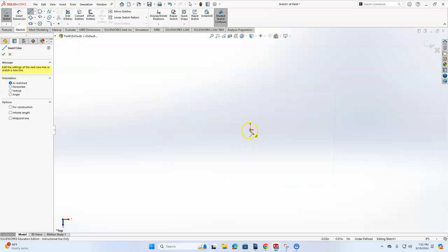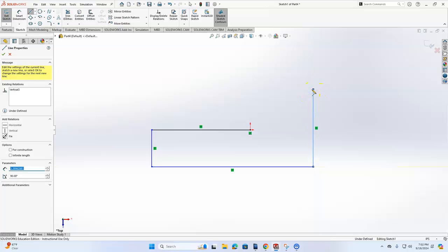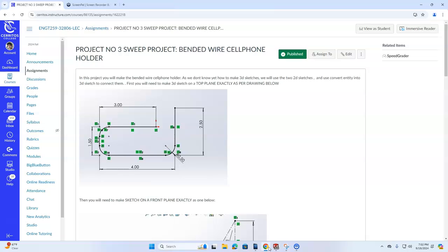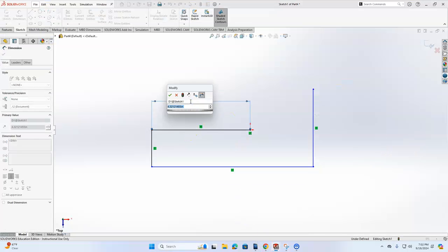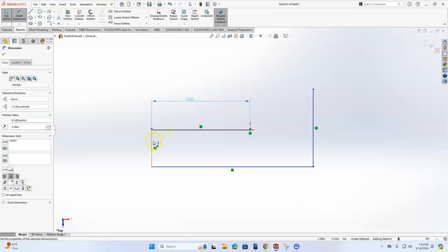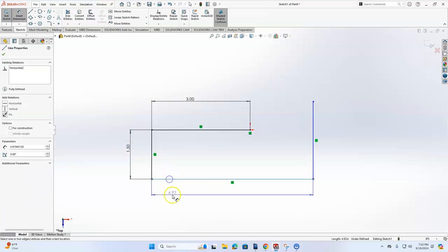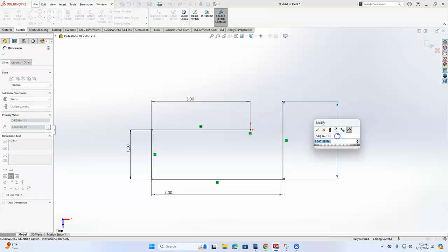Going to make a horizontal line left from the origin, then I'm going to make a line down, all horizontal and vertical, and I'm going to start putting in the dimensions like 3, 1.5, 4, so 3 inches, 1.5 inch, 4 inch, and back is a 2.5.